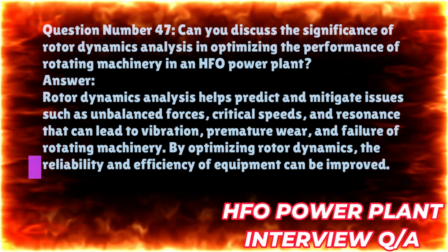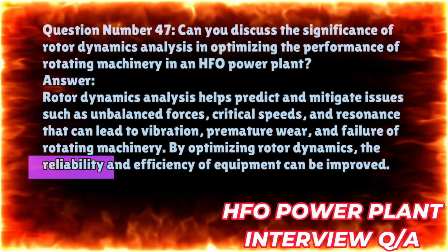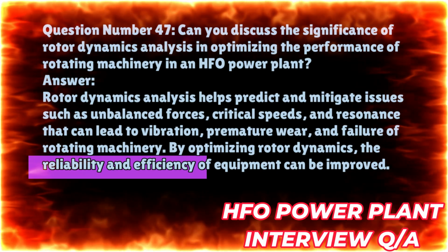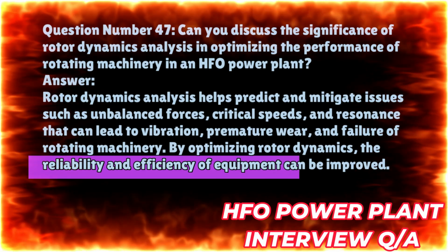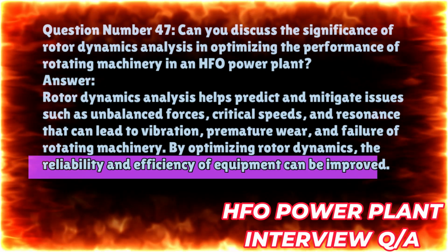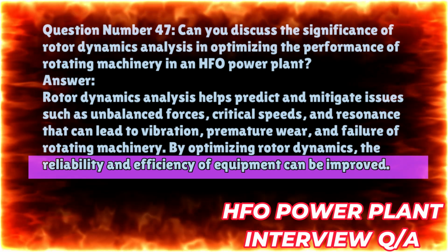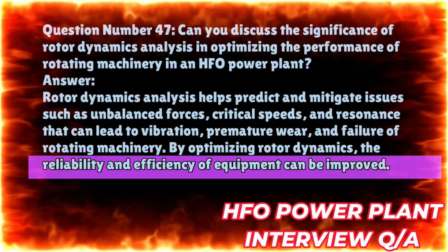Question number 47. Can you discuss the significance of rotor dynamics analysis in optimizing the performance of rotating machinery in an HFO power plant? Answer. Rotor dynamics analysis helps predict and mitigate issues such as unbalanced forces, critical speeds, and resonance that can lead to vibration, premature wear, and failure of rotating machinery. By optimizing rotor dynamics, the reliability and efficiency of equipment can be improved.